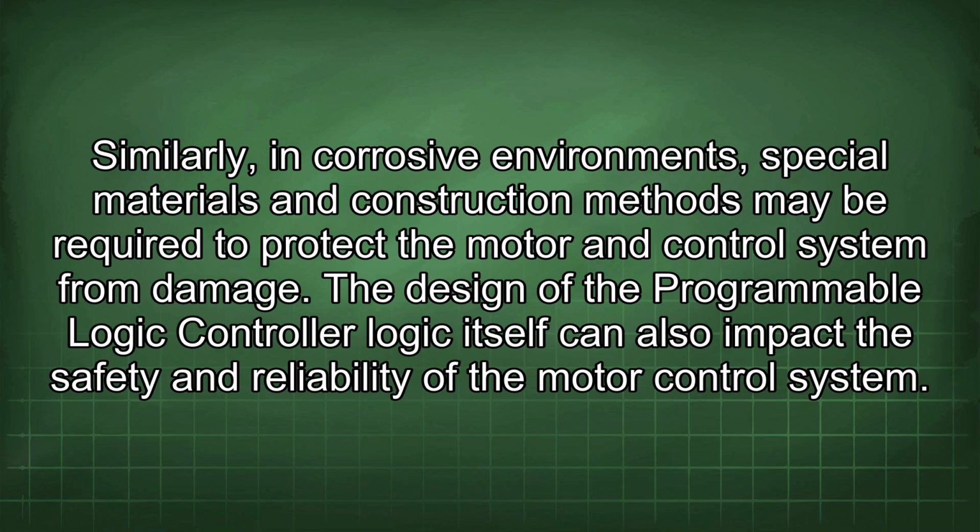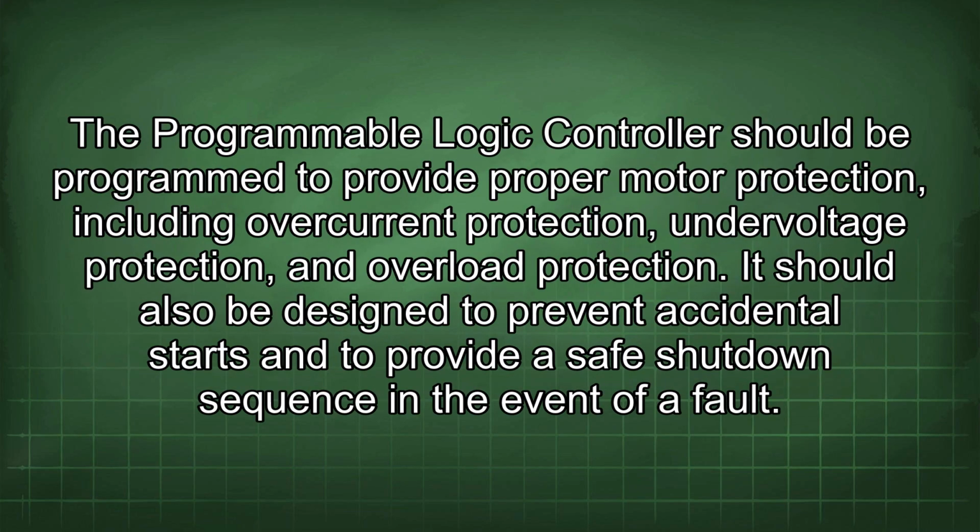The design of the programmable logic controller logic itself can also impact the safety and reliability of the motor control system. The programmable logic controller should be programmed to provide proper motor protection, including overcurrent protection, undervoltage protection, and overload protection. It should also be designed to prevent accidental starts and to provide a safe shutdown sequence in the event of a fault.